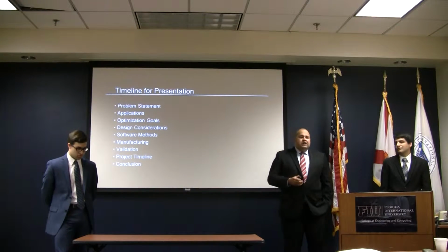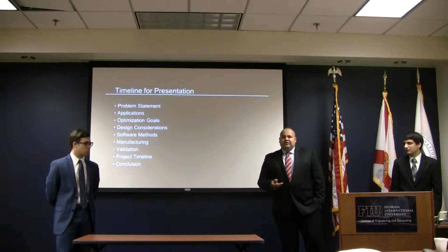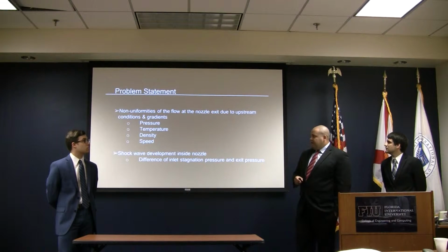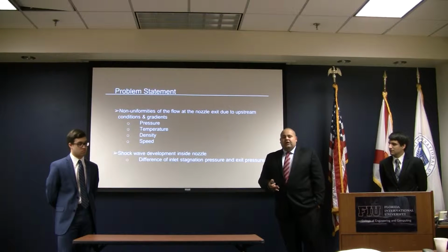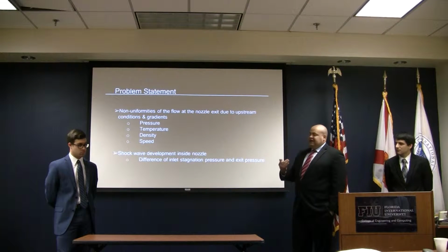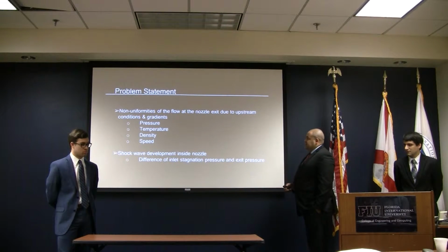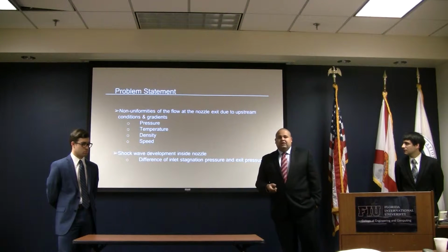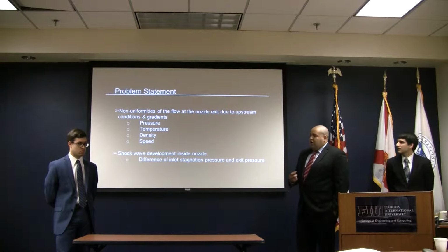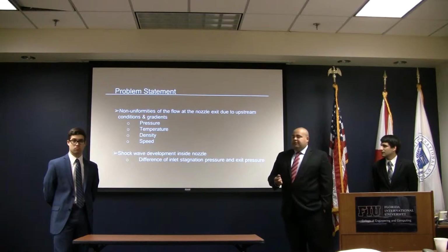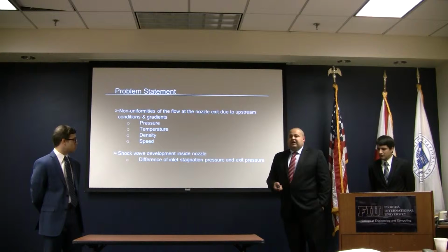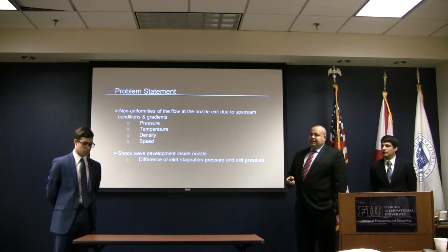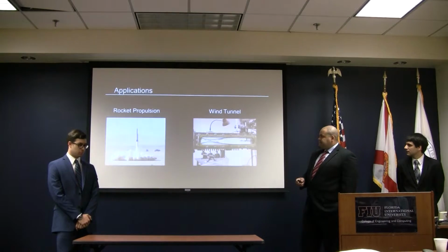Timeline for our presentation: I'll talk to you about our problem statement, our applications, our validation, and some considerations for this project. Now, our problem statement. There are non-uniformities in the flow at the exit of the nozzle due to upstream conditions such as pressure, temperature, velocity. Also, we're going to be looking at shockwave development inside the nozzle. Shockwave typically starts from the difference of stagnation pressure and the exit pressure.